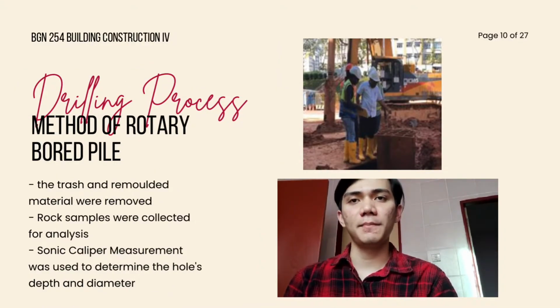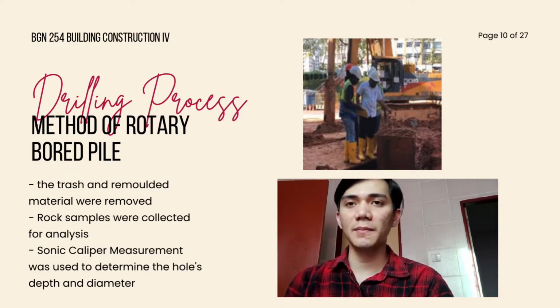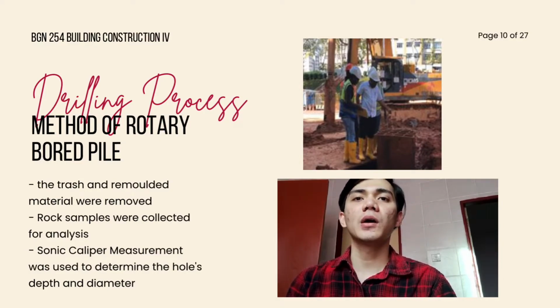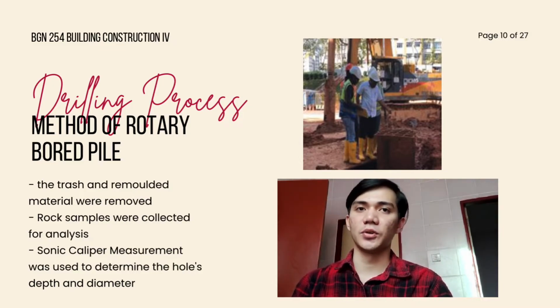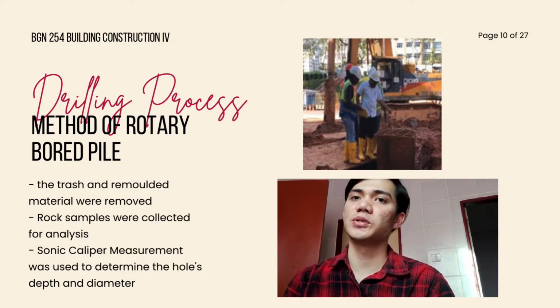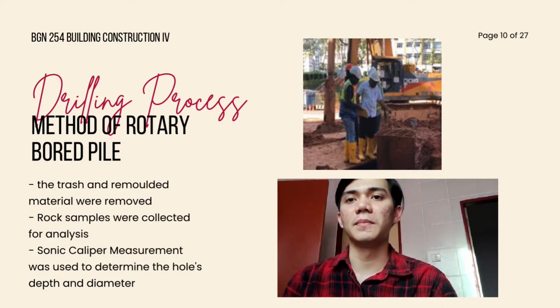Once at the desired depth, the trash and remolded material were removed. Using a cleaning bucket, rock samples were collected for analysis. Sonic caliper measurement was used to determine the hole depth and diameter.